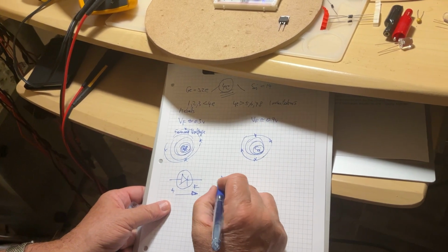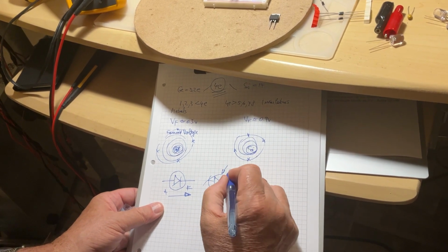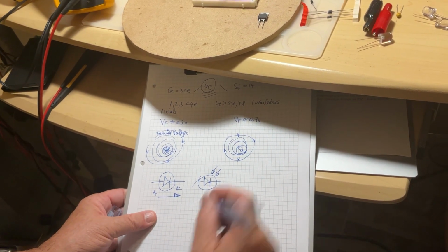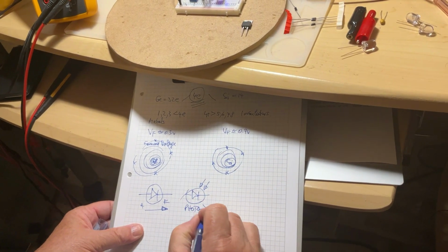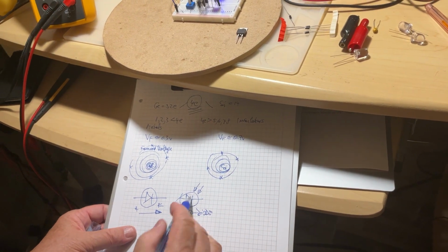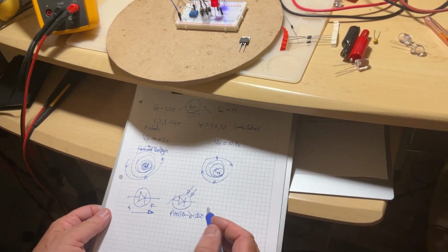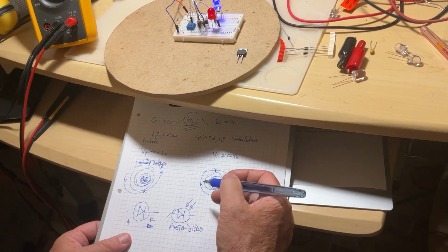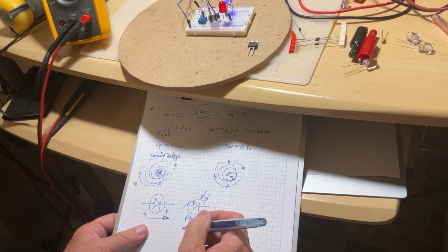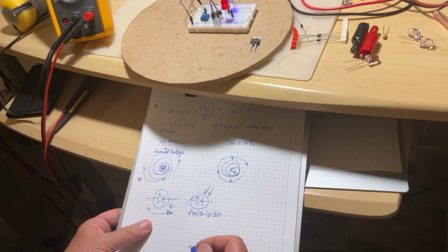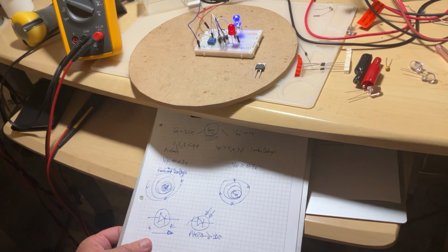But if you see such a symbol over the diode, like this, 1 or 2 or 3 arrows going to the diode, that's a photodiode, exactly like the solar cells, everybody knows. So silicon is capable of converting a fraction of the energy coming in the form of light into electricity, but is not capable of converting the opposite, electricity into light. This is why they had to find other materials.